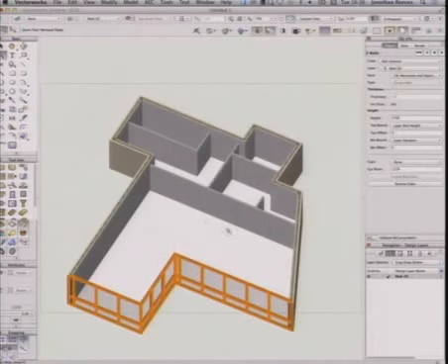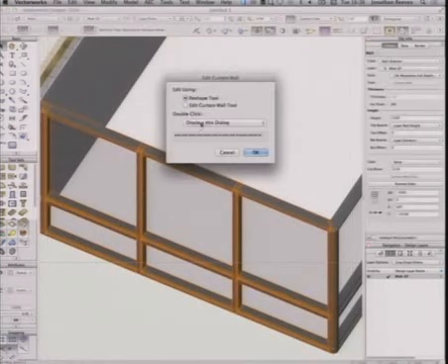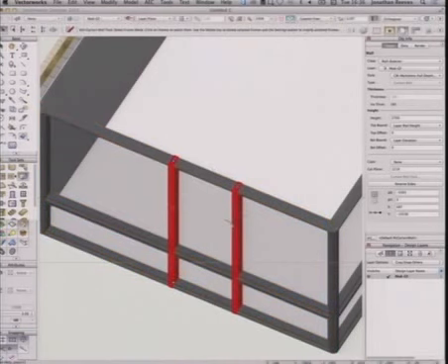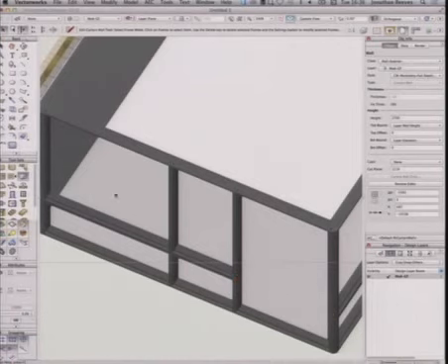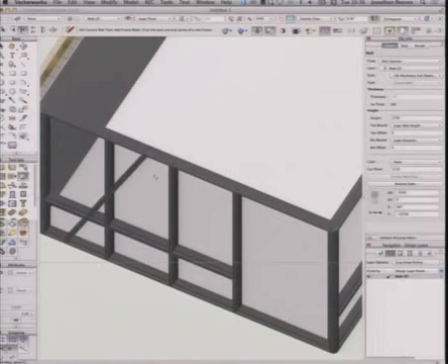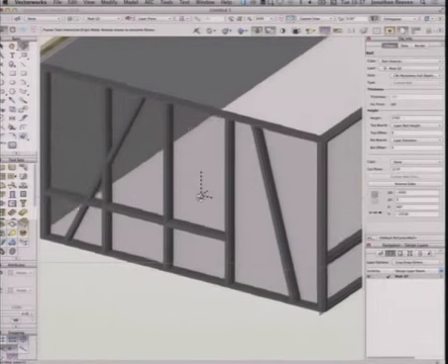And the beauty, as Samit showed earlier, I think, with the curtain wall tool, is that it is really, really flexible. You simply double-click on it, and you can either reshape it or edit the curtain wall. You can add bits in, you can move, delete mullions, so if you want to delete that one, it's fine. No problem. You can have quite a lot of fun with it and be really creative. And I think this came in last year in 2015. It gave an inkling into where Vectorworks was heading, a creative method of customizing, creating curtain walling, that sort of thing.